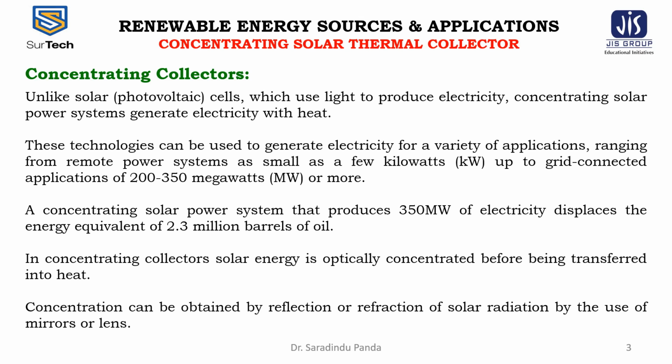Concentrators can be reflectors or refractors, can be cylindrical or parabolic, and can be continuous or segmented. Receivers can be convex, flat, cylindrical, or concave, and can be covered with the glazing or uncovered.